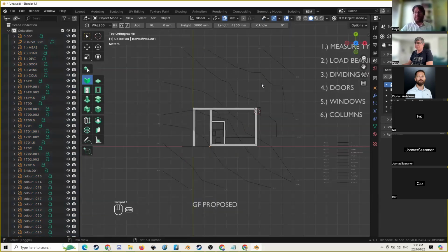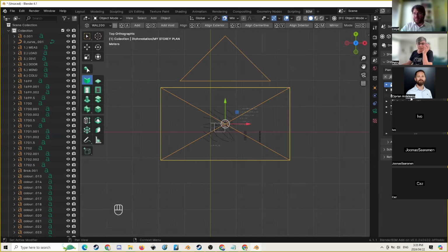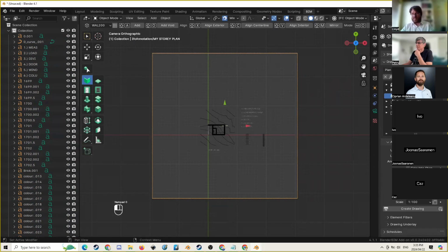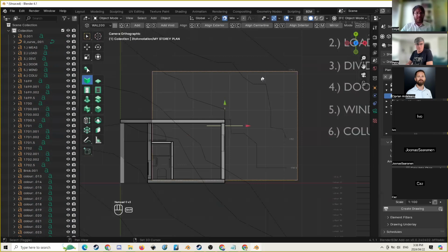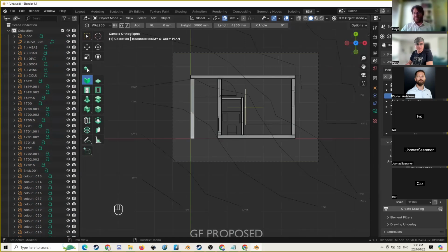So we had an error with our plan. I'm just going to create the plan again and my story, select it, activate it, and then go to our active drawing and change this to 8 meters, and this to 6 meters. This is just my preference. Then we bring it aligned roughly there and turn our snaps back on. We check it works, activate, and print the drawing. And there we go. Okay, brilliant. So that's where we are. I'm going to make it 1 to 50.